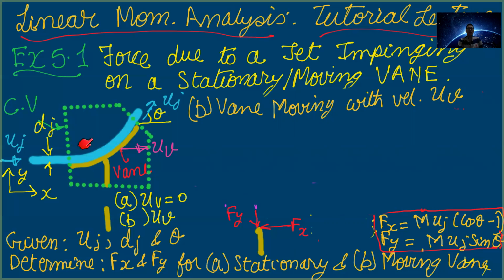For the moving control volume, when we consider the velocities entering or leaving the surface of the control volume, we have to use a relative velocity. To calculate the relative velocity, note that one velocity appears when calculating the mass flow rate, and another appears when calculating the x momentum flow rate and y momentum flow rate. For Fx, the x momentum flow rate, along with the mass flow rate, the velocity is the u velocity, whereas for Fy, the y momentum flow rate, the vertical velocity v appears.